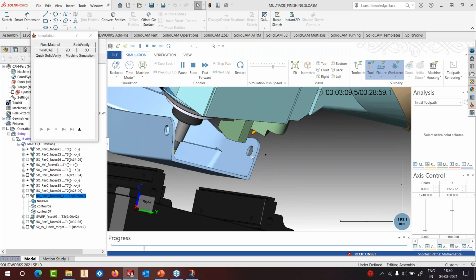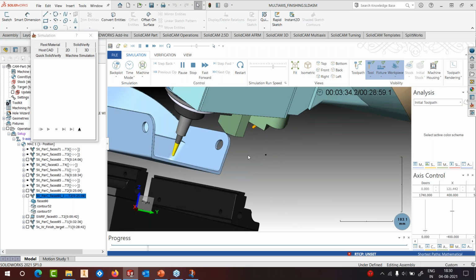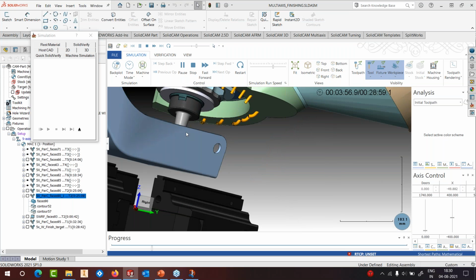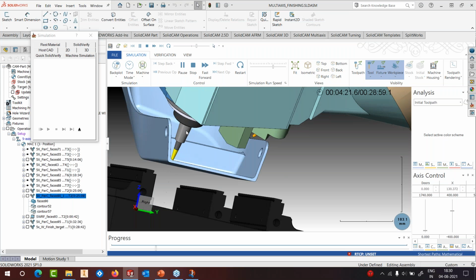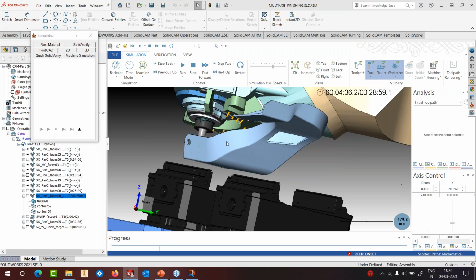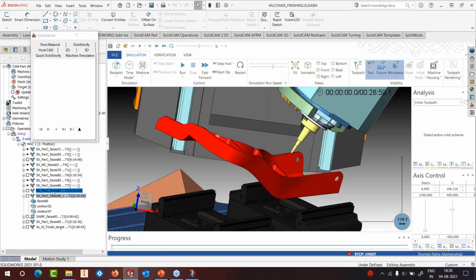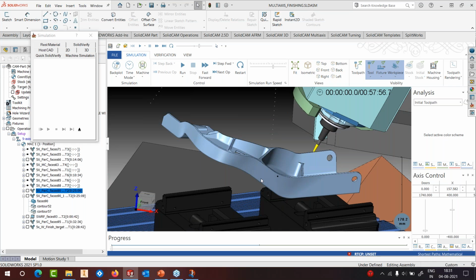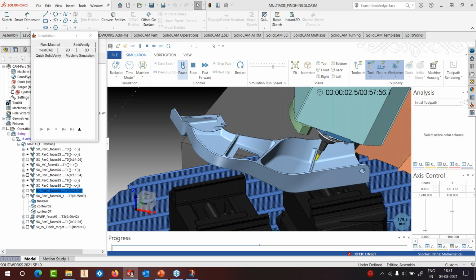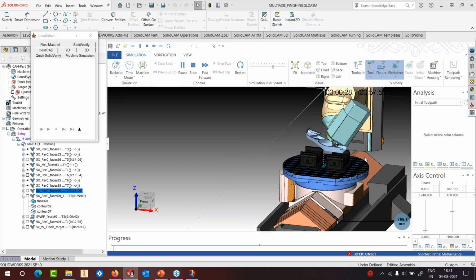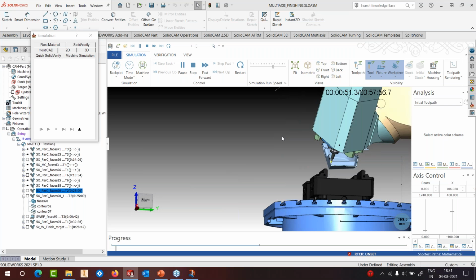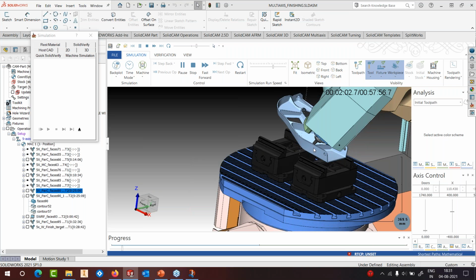So one of the remedies here is to increase the holder length in such a way that we get completely different tool path. The other remedy here is to change the tilt control itself. So I have got the earlier one, which I have defined, the tool path. I have got the curve on a completely different plane. And you can see that, sorry, I don't have any collisions as such. There's no more collision because I've used completely different plane here.